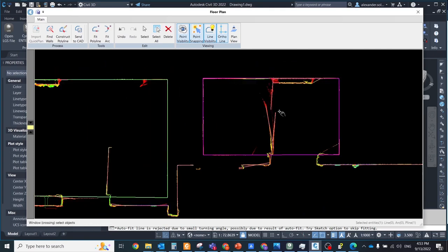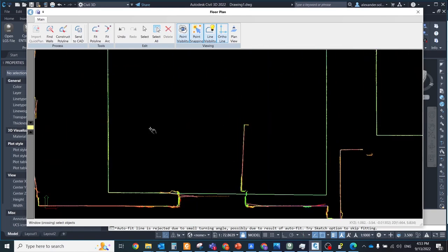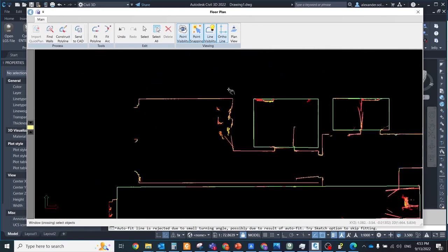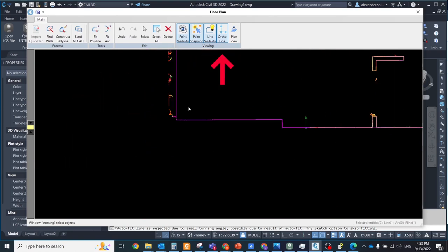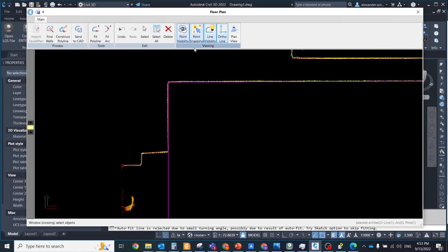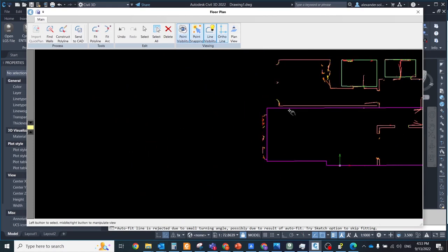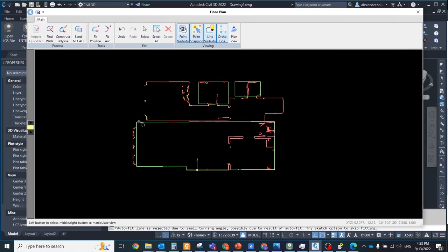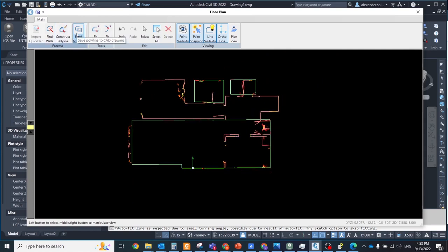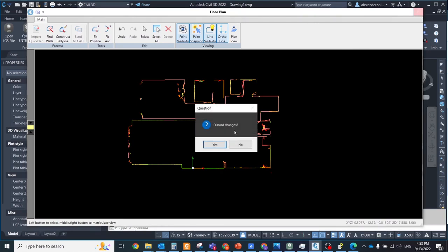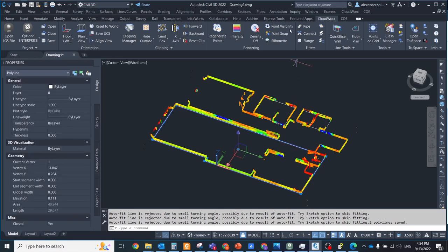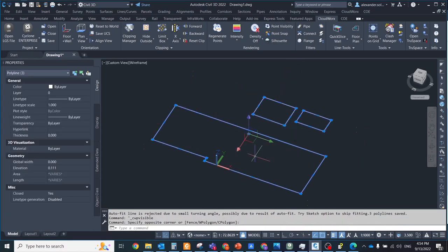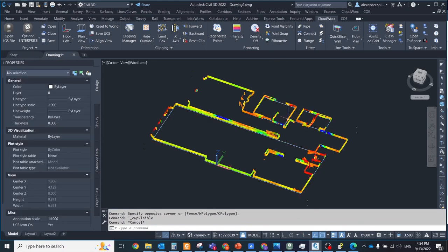Connected drawn segments will try to grow automatically if the Auto Advanced option is enabled, and will also refine as new segments are connected or created. With ortholine mode enabled, all corners will be 90 degree angles. After ending or closing the polyline, it will turn green. Green polylines may be selected and the endpoints can be adjusted to fine-tune your line work or to correct errors. Send to Cut pushes the finished polylines, shown as green lines, back to your current drawn model and closes the tool. Any remaining red line segments will be discarded and ignored.